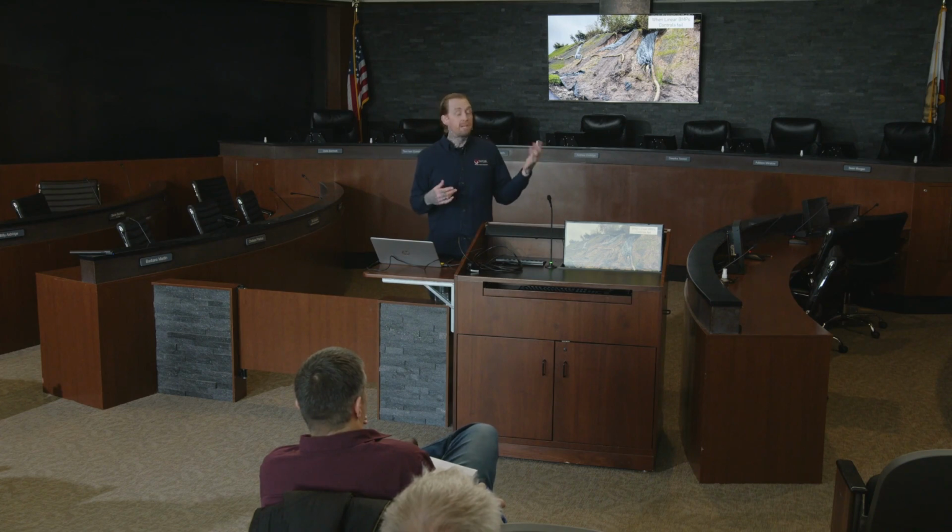But I show this because sometimes you can do seemingly everything right and Mother Nature will just get the best of you. This would be a case of, as an inspector, you have a totally disastrous hillside and yet your contractor seemingly did everything that you asked for, put the plan into place, maybe even went overkill, and still you have a disaster. So this is where you wouldn't want to be such a tough guy and break them off really badly. You'd want to give them some time to fix this, because obviously they need to fix it. It's a disaster, but it just goes to show you that you can do everything right and still have BMPs fail.